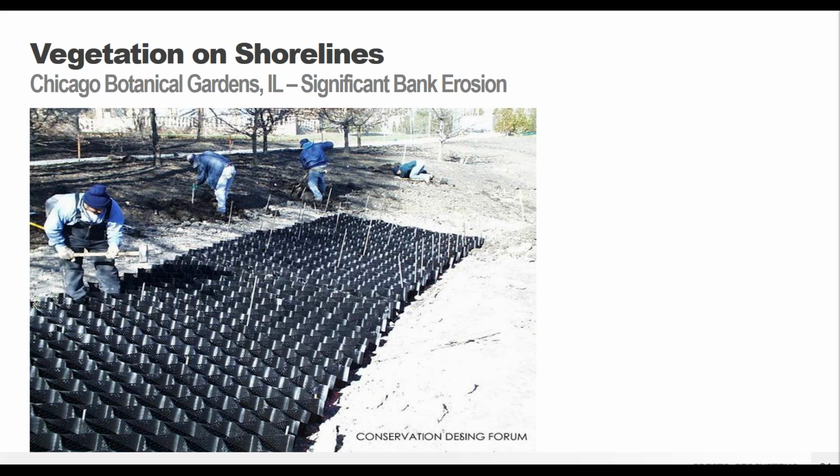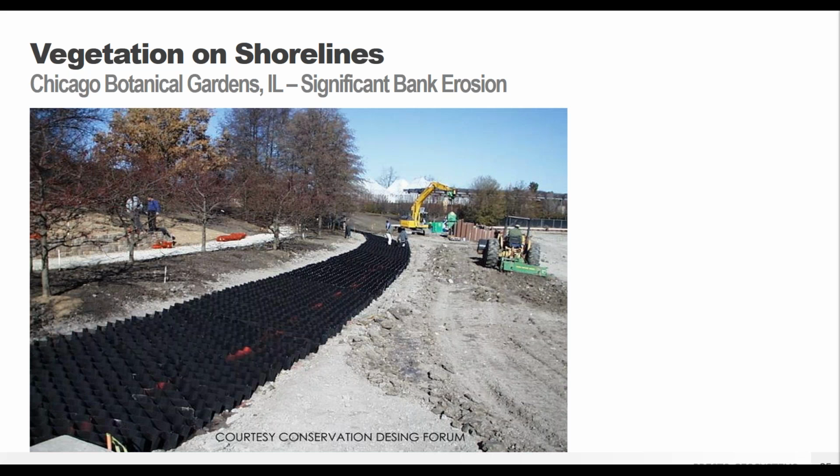They went through and de-watered the pond where this was. And they can do that because it was at the Botanical Garden, so it's a sort of maintained pond, but they were able to de-water it so they could do everything in a dry environment. You don't necessarily have to do that. You can work in a wet environment if you don't have dewatering capabilities, but I'm sure it makes your crews happier not to have to stand in water to do that.